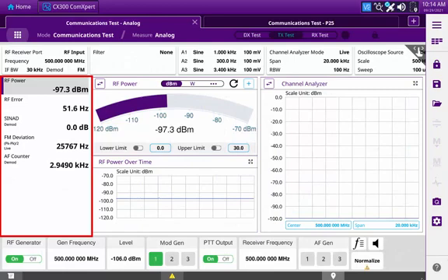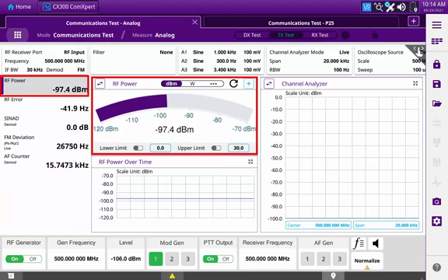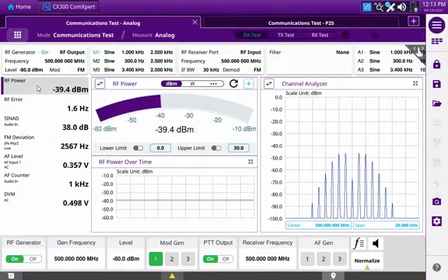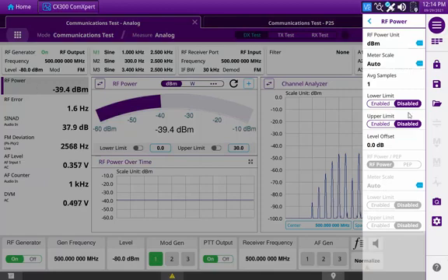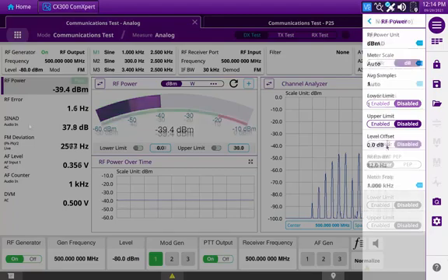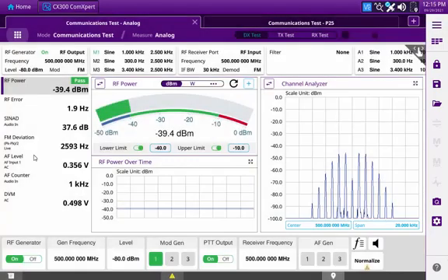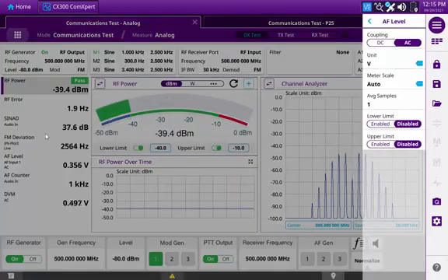The Meter Reading pane provides a quick view of meter readings. The meters displayed in this area depend on the mode of operation, the demodulation type, and noise meter selections. If a meter is selected for display as a swept meter, the meter display in this pane will have a gray background. Like the Test Settings toolbar, the Meter Reading pane provides a means to directly select the submenu that controls the settings of the meter simply by selecting the meter. Color-coded pass-fail states are visible in this pane for any meter that has its limits programmed and enabled.